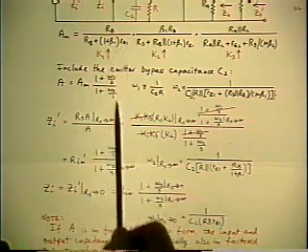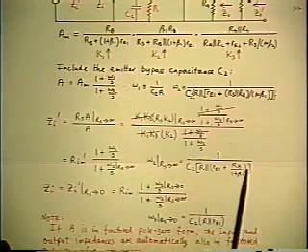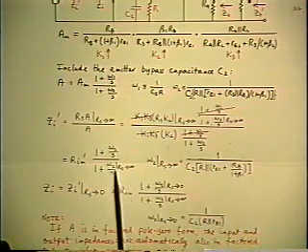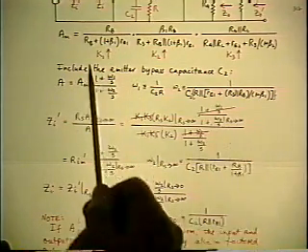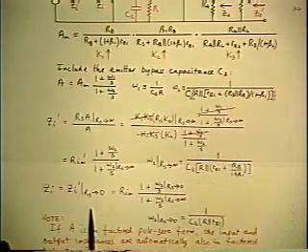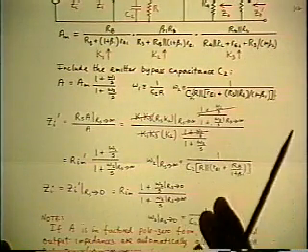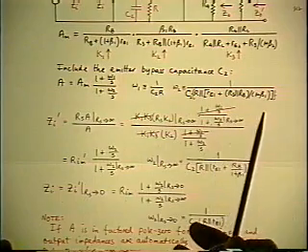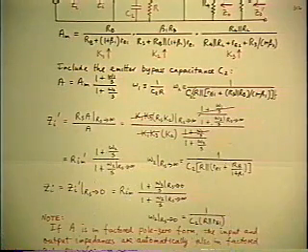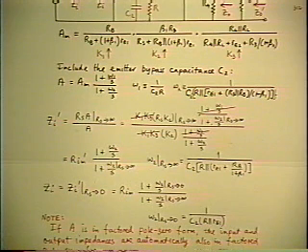So what the frequency response does to the application of the theorem is you just treat a pole or a zero just like any other factor in the A. If it doesn't contain Rs, it cancels. If it does contain Rs, you just get a new corner frequency, that's all. So it's still pretty easy.